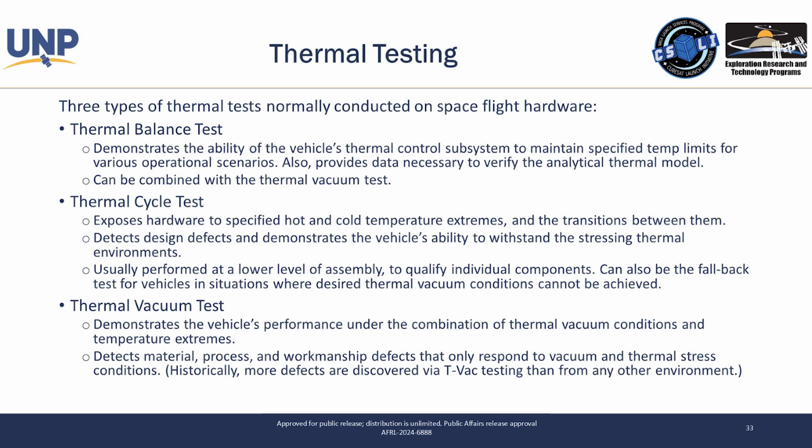So we'll do a thermal balance test where you just put it in vacuum and turn it on and see what temperature everything hits. You'll cycle it to actually get that mechanical stress of heating and cooling, expanding and contracting all of your joints. And then thermal vacuum, where you'll cycle it in vacuum. And those are the things that find those material, process, and workmanship defects that are only going to be present when you're in that full final environment. And this is where really you find the most fiddly, difficult, and nuanced problems.